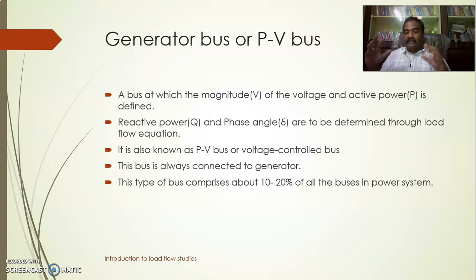So what I am doing is keeping a generator bus aside. Now my generator buses are 19 and I have 80 load buses. These 19 positive power injections are equated to my 80 negative injections. So generation is equal to demand, plus losses. These losses are covered by an extra generator which is capable of generating the power. In this way load flow study is carried out. So of all the generators, one bus is kept aside and treated separately in order to cater to the losses of the system. It is just an assumption.